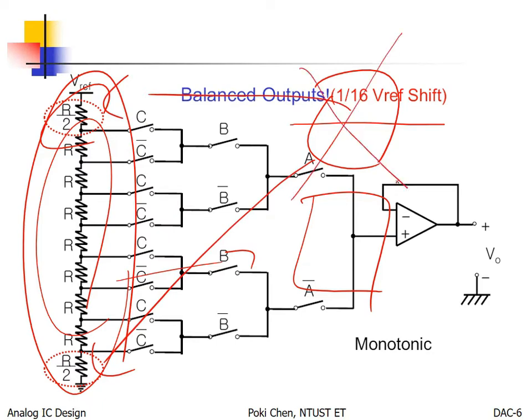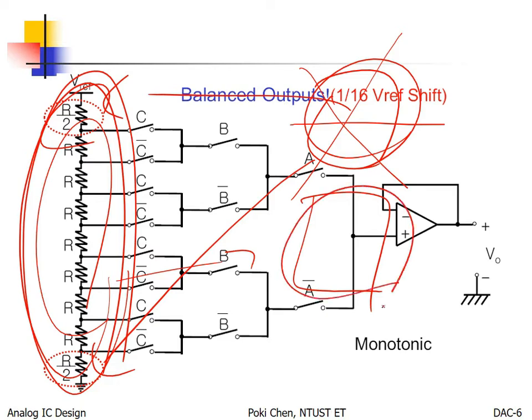However, it is no good. If you would like to make it, I hope you don't do such silly things, right? If you would like to match all of them, because everybody is important to provide the best voltage division, close to optimum, close to perfect, then you need to apply unit resistors for everybody. Keep this in mind. Not only for R, but also for R/2.